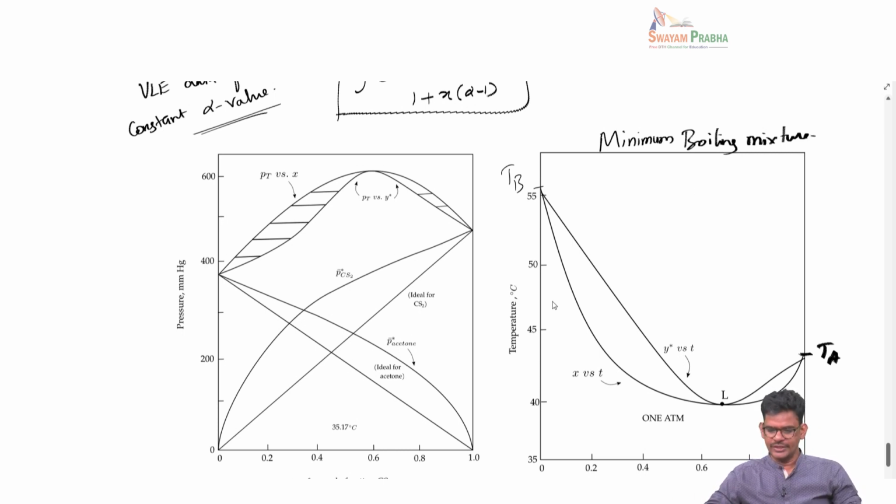And what is also interesting is that this happens because the mixture's total pressure goes above the respective partial vapor pressure. Consequence of that is that the boiling happens at a lower temperature than either of the normal boiling points here. Okay, so point L here is where both the curves are touching each other, and this leads to what is called an azeotrope.